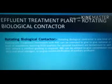And next, coming to the RBC, the rotating biological contactor. A rotating biological contactor is one kind of treatment system. A treatment system with RBC can be designed to give secondary or advanced level of treatment, with effluent BOD quality values for secondary treatment comparable to a well-operated ASP.